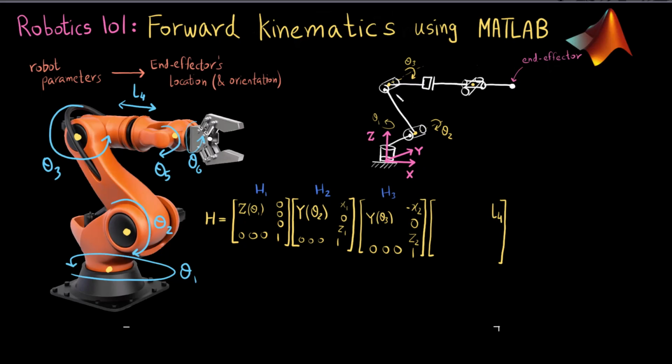It is not fixed for the robot, but it can move as desired. So this is A4, let me mark out A4 so there is no confusion. A4 goes from here to here. So there is going to be a displacement by A4 in the x direction, no displacement in y, no displacement in z. Then there are 3 zeros in the bottom row and a 1.